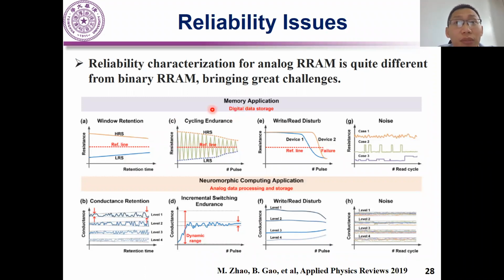For binary RRAM, we only focus on whether the resistance window exists or not. However, for analog RRAM, we have to monitor the conductance change at any time point. So for retention, disturbance, and noise tests, it's much stricter.